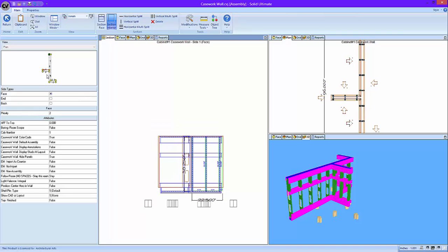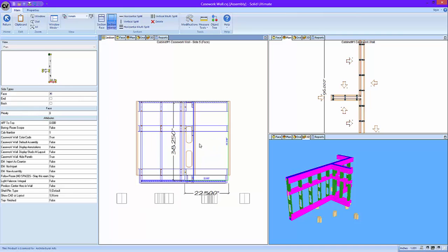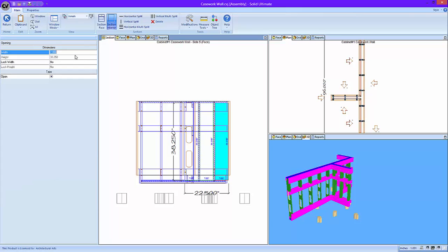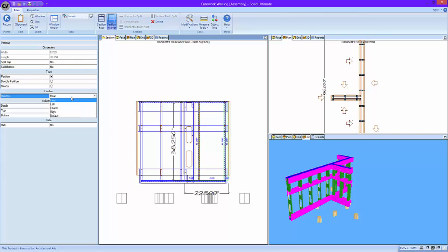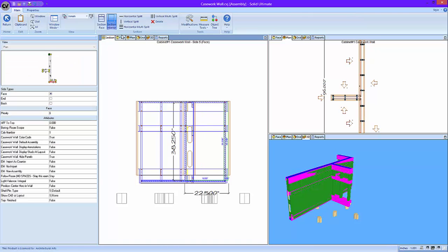Okay. And we will pop over to this end. We'll add our 3 partitions. Pretty much the same process here. We need 1.5 inches there because we have our toe notch. And we'll send this to the left. Alright, and that is too far.